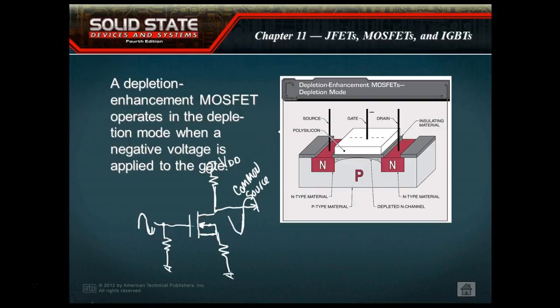So this is a lot simpler amplifier as far as biasing, very easy to bias. It's almost got infinite input resistance. All we have is a leakage current, kind of like we have in an electrolytic capacitor, which is too small for us to measure. We can set our input impedance with a resistor right here to whatever Z I want. Normally this guy is going to run a high impedance source into a lower impedance load. And that's just basically what they do.